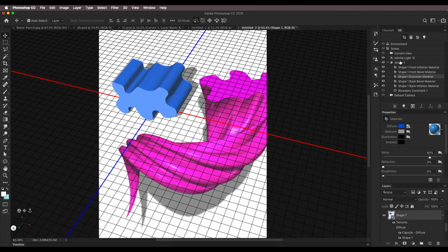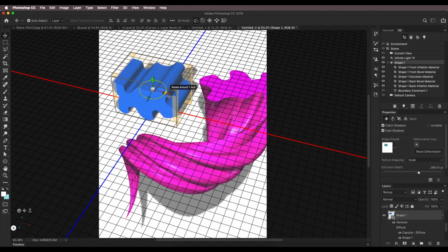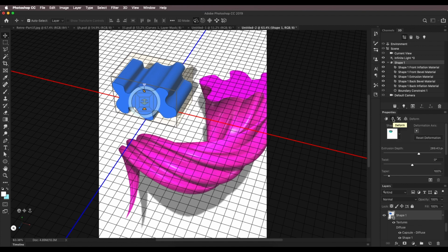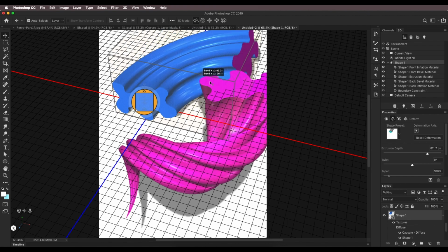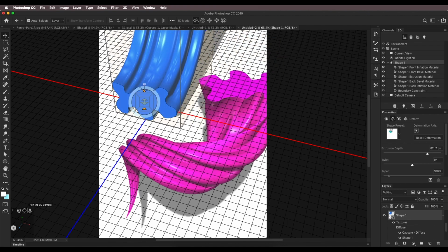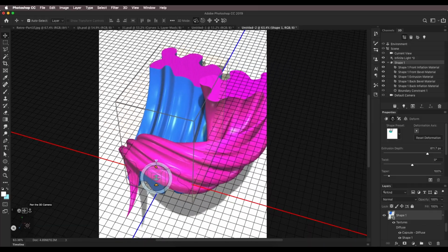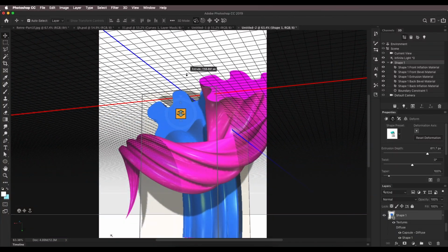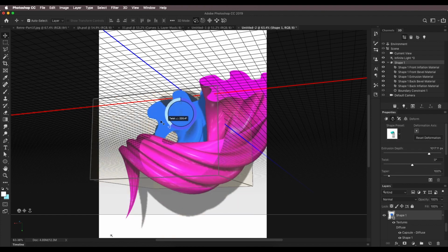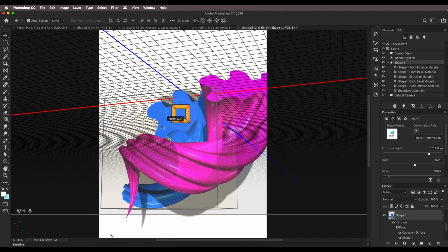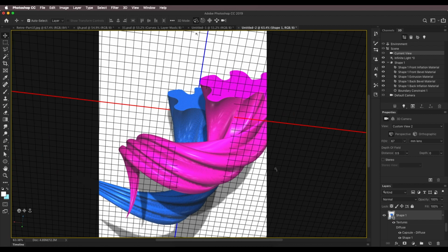And now we're gonna do some tweaking using the attributes. So selecting this shape, select this option here, and this is mesh, this is deform. So this is the deform option. By selecting this, you activate these attributes. So let's extend a little bit, right? And then you can give a little bit of click and just rotate it around. I'll just place it in the center around here, or maybe we'll just rotate it like this completely. Selecting the deform option and selecting this, just twist it, make the corner pointed, and just keep on tweaking it until you get the desired look.